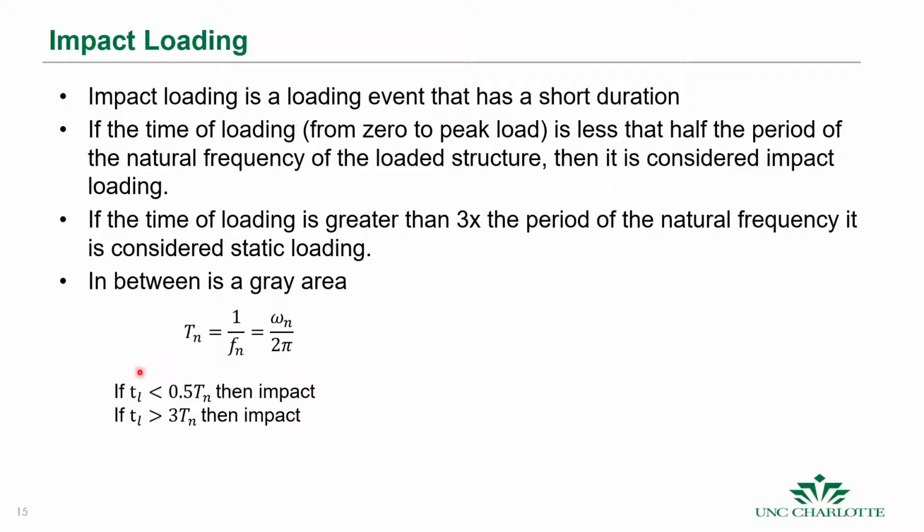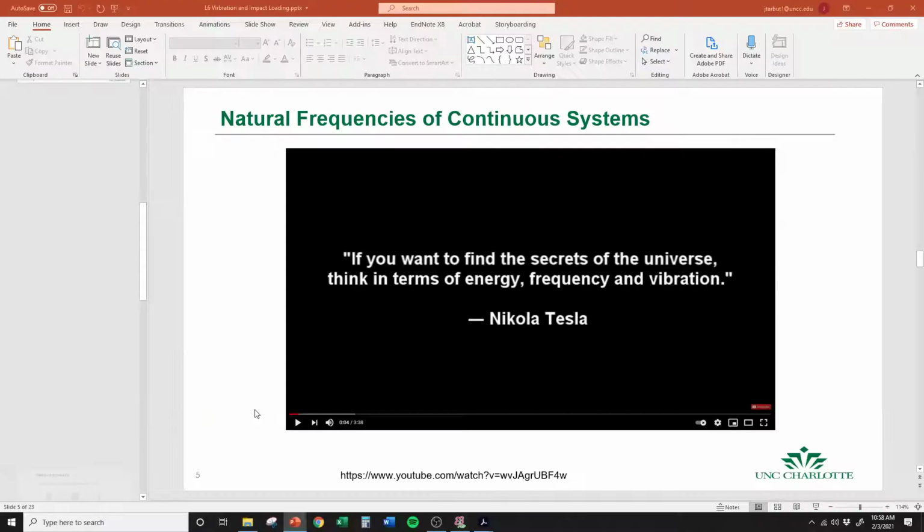So this is a summary. If the time to the peak load is less than half the period of the natural frequency, we consider it impact. If it's greater than 3 times this period, then it's considered static. Okay.